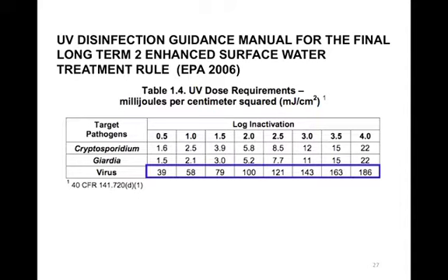One of the reasons is that if you use chlorine and then discharge your wastewater to a sensitive receiving body, you often have to dechlorinate. Whereas if you apply UV, you don't have to worry about that, and the UV doesn't leave a disinfectant residual, so that can actually be an advantage. So UV has become quite common for disinfecting wastewaters. It's more common for disinfecting wastewater than it is for drinking water.